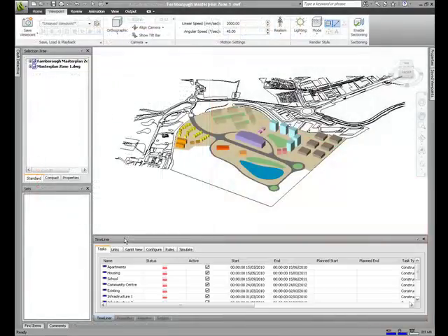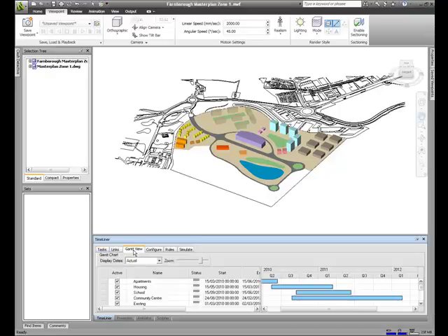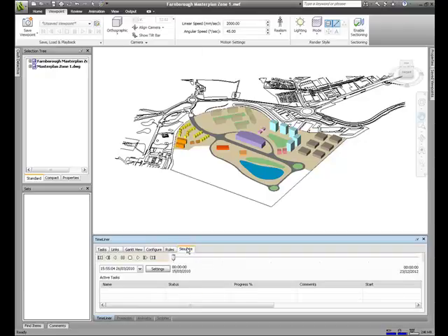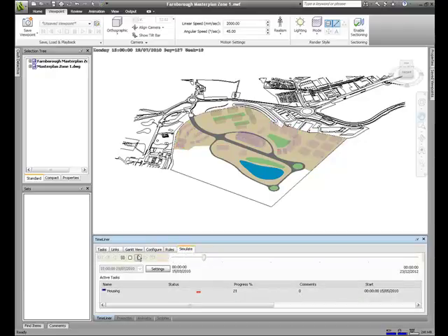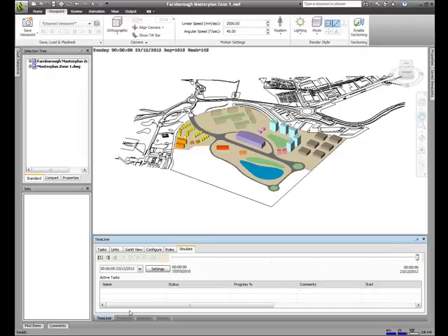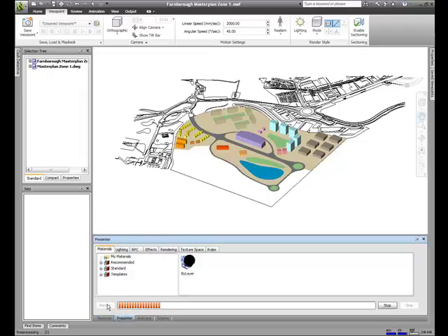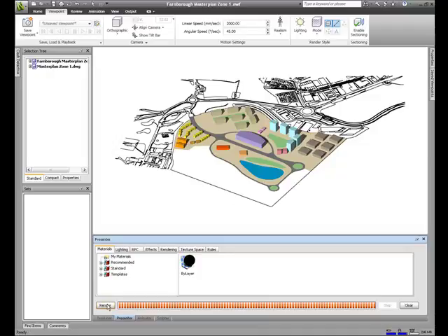Moving over to the master plan model, of which our school building is part, we can see how Navisworks timeliner functionality can be applied not just for construction sequencing simulation, but also for visualizing zoning when master planning. Here, timelines have been applied to various zones, and we can watch as the model builds up over time. Finally, using the presenter functionality, we can render the scene. Both of these can provide a significant benefit, especially for public consultation or planning requirements.